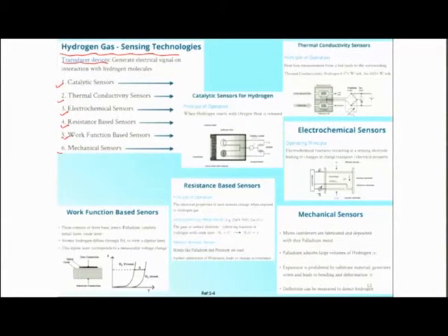So, the catalytic sensors for hydrogen typically mean that you are burning hydrogen in the presence of oxygen and measuring the heat release. So, if we have a standard hydrogen, basically in this particular case we compare a known concentration of hydrogen and the heat that it releases with respect to the unknown concentration of hydrogen in two different modules here.